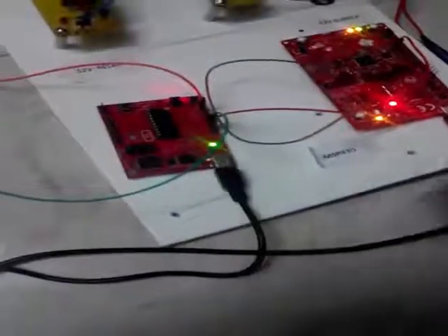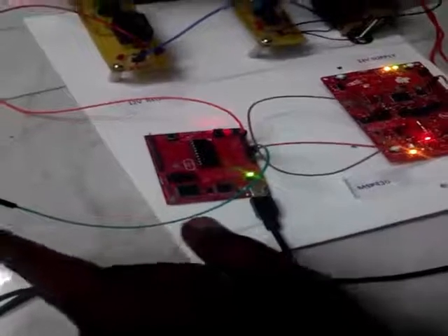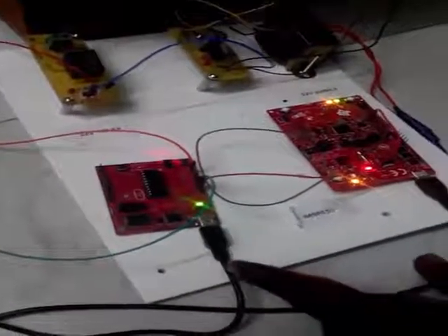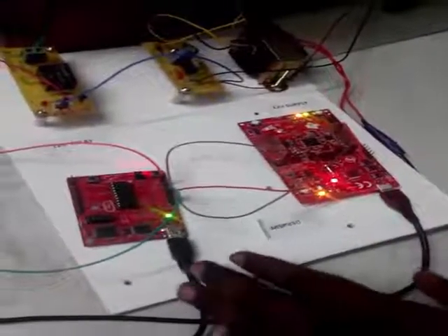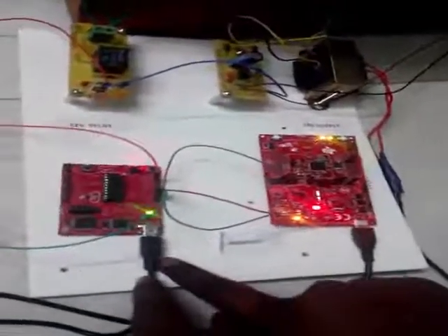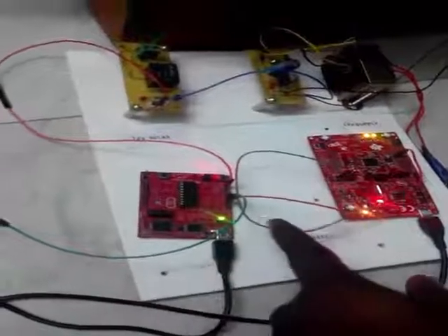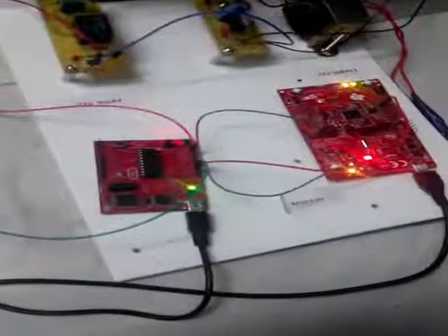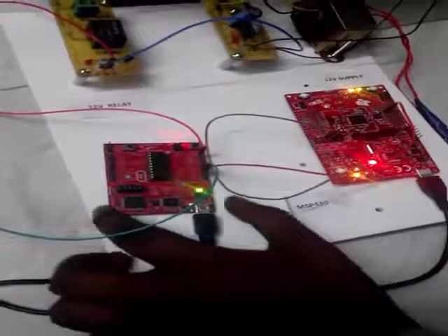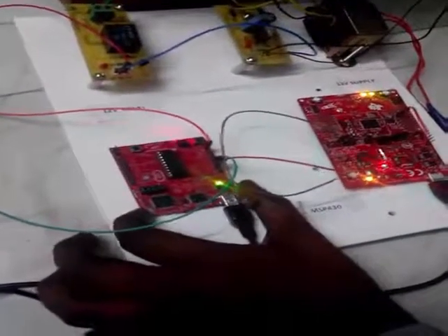The main reason we went for this MSP430 is that using this EZ430 we can easily build a WSN network, that is a wireless sensor network. Just for this wireless sensor network we use the MSP430. We have connected one TI IC of this access point to the MSP430, to a UART. Likewise, several EZ430s can be connected here and can be monitored. That is the main reason why we went for the MSP430 part here.